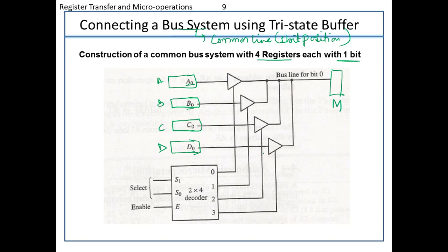what will happen in this case is that I will be using a 2 to 4 line decoder. The reason being, here I have the number of registers equal to 4. So how will this help me? These are the two input lines. We know how decoders work: for 0 0, D0 will be active. For 0 1, D1 will be active, or the first value will be active. For 1 0, the second value will be active. For 1 1, the third value will be active, right?